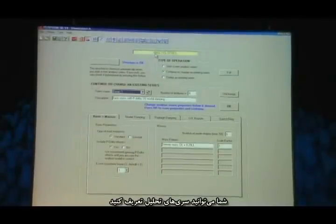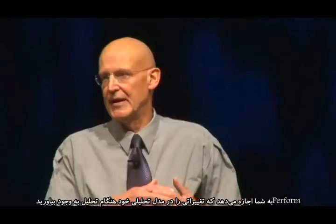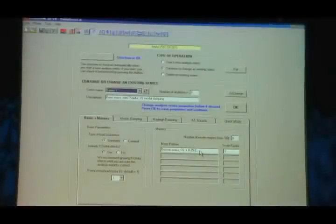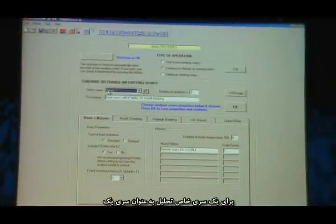You can then specify what is called an analysis series. And let me spend a little while on here. You're going to run some analyses, but what Perform allows you to do is to make some variations in your analysis model at the time that you do the analysis. For example, here we're specifying some masses, and this is a particular analysis series called Series 1.